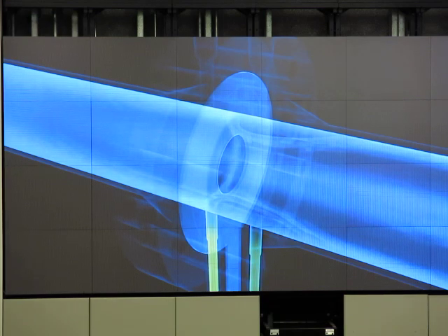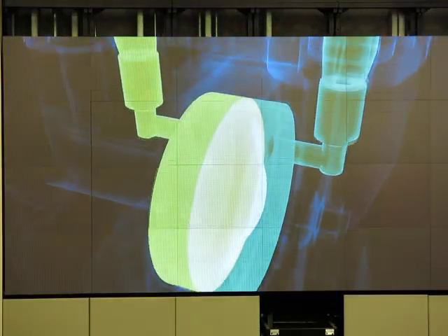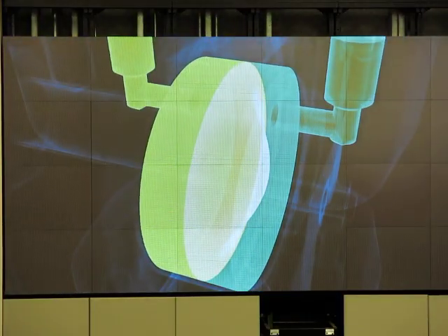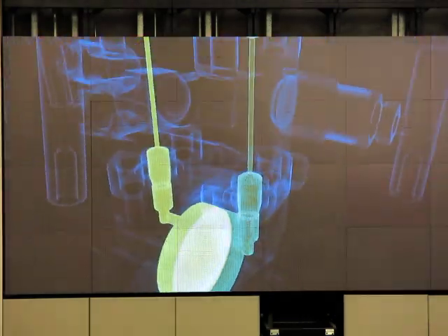As soon as the fluid starts to flow, its velocity around the orifice plate increases significantly because of the restriction in the cross-section. At the same time, due to the laws of fluid mechanics, the static pressure at this point decreases. Consequently, different values are detected in the pressure chambers of the sensor, a higher pressure before and a lower pressure after the orifice plate.